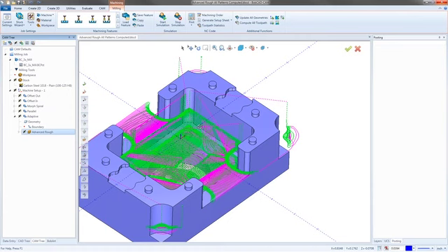So what normally takes me 4 passes to get down to that depth is not going to take me 1 to that depth, but a lot more step overs. You can kind of determine which one you want. I like this method a lot because it's going to let my tool wear a lot more evenly. I'm not burning out just the bottom 1/4 inch of my tool. I'm burning out the entire length of the tool across the whole thing. So this is a really good option to save tooling, to make sure you don't do any really weird movements all around. It's a really pretty safe toolpath, and you can see it's going around doing all its cuts.